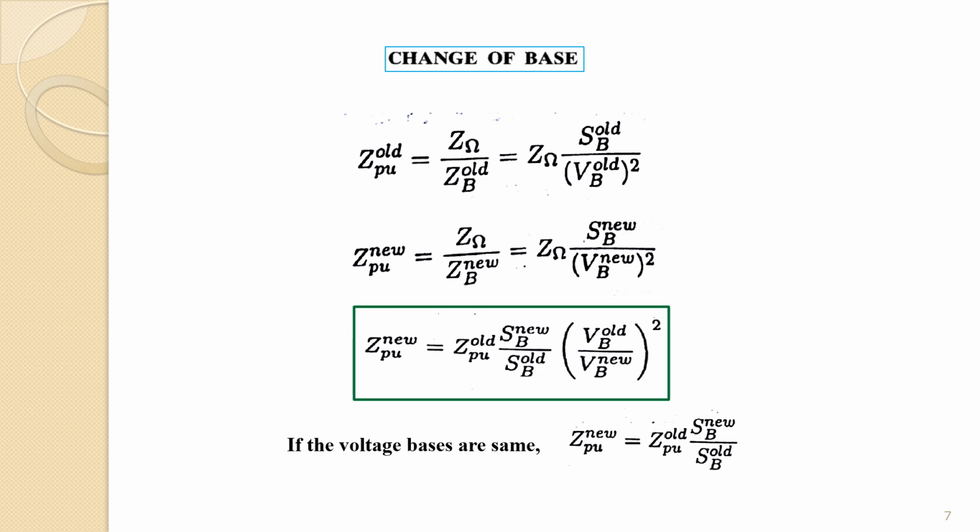The impedance of individual generators and transformers as supplied by the manufacturer is in general based on the generator or the transformer ratings and usually expressed in terms of percentage or per unit quantities. The impedance of a transmission line is usually expressed by its ohmic value. So all the impedances must be expressed in per unit on a common system base.